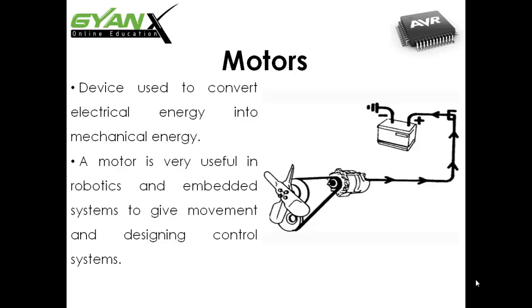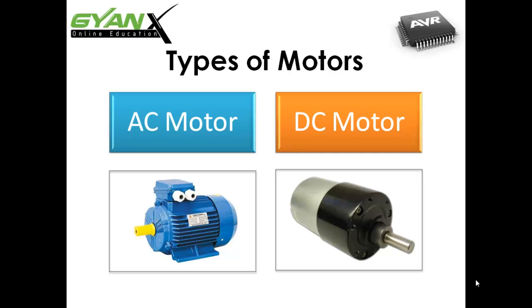In normal motoring mode, most electric motors operate through the interaction between an electric motor's magnetic field and winding currents to generate force within the motor. In certain applications such as the transportation industry, with traction motors, electric motors can operate in both motoring and generating or braking modes to also produce electrical energy from mechanical energy.